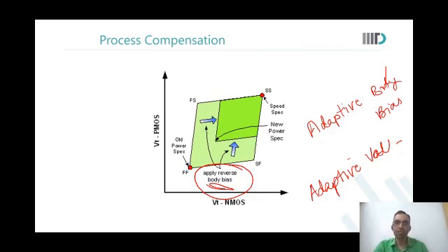Okay, so these again are areas of active research. There is lots of work happening. These technologies are even in production, where dies are trimmed to operate at lower voltage or higher voltage depending on where they were manufactured. So at the time of test, you see what is the operational frequency and you trim them. What is the leakage and you trim them appropriately.